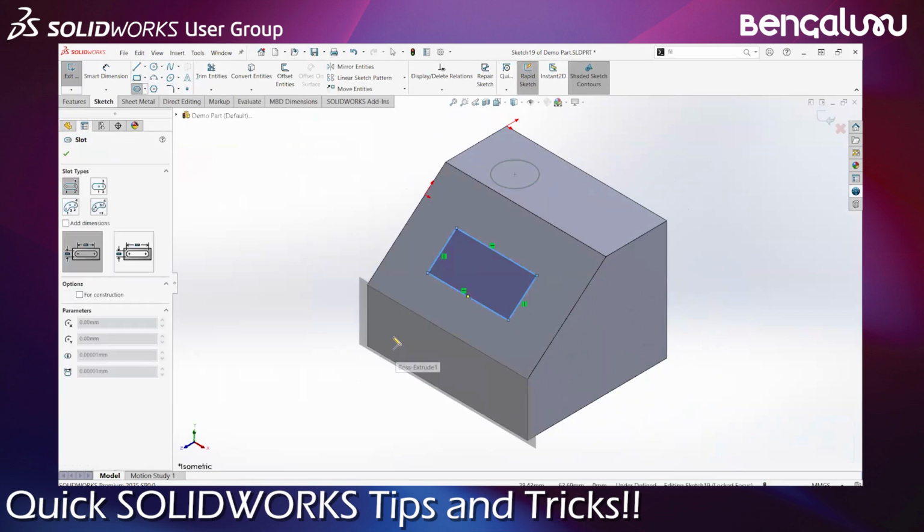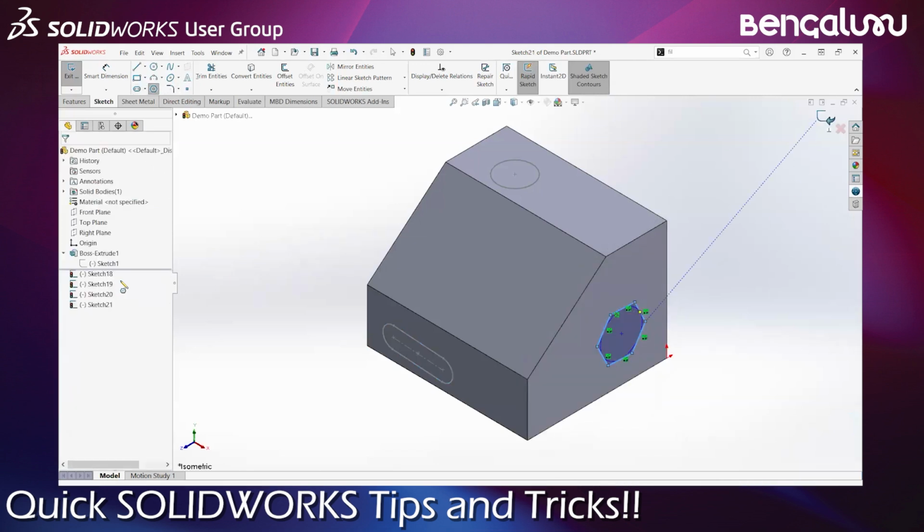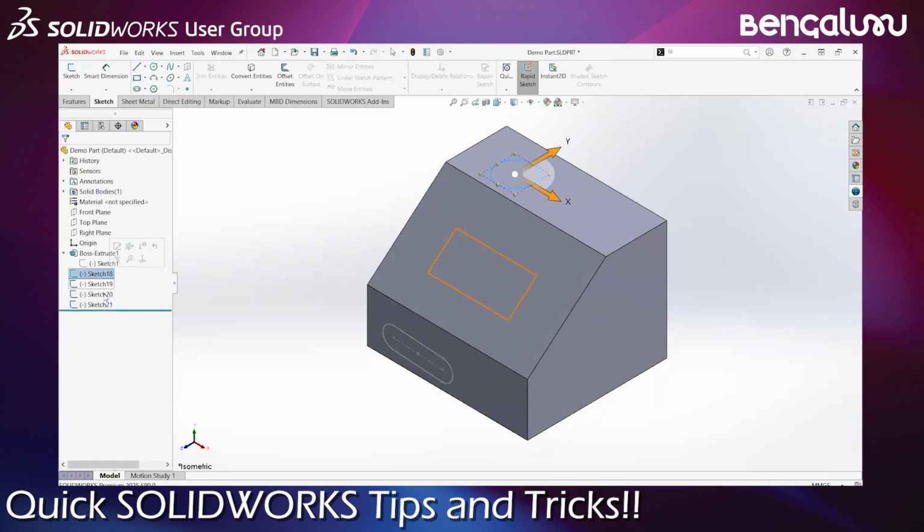You see SolidWorks automatically identifies that this is the face you want to draw on, and when you draw a sketch, it is actually adding it on that face. And maybe on this one I'll just add a hexagon. Now if you see in the feature manager tree, it has actually created 4 different sketches. That is what you would do anyway if you wanted 4 different sketches.